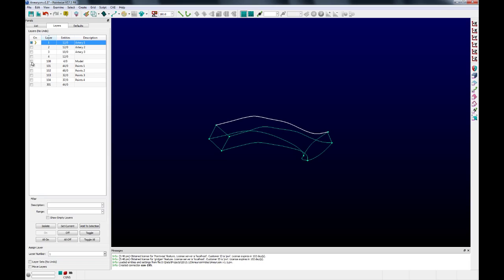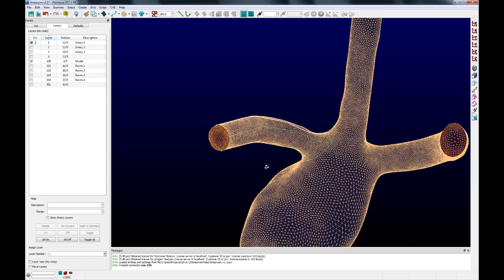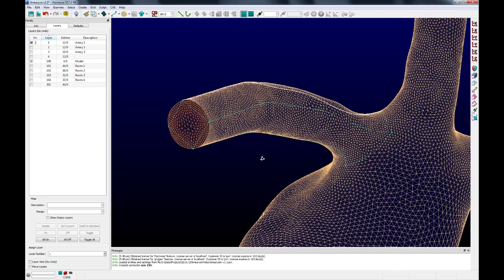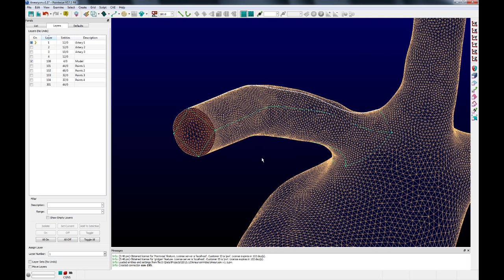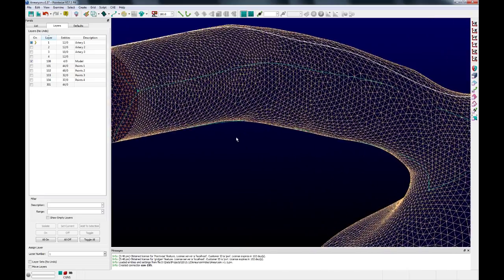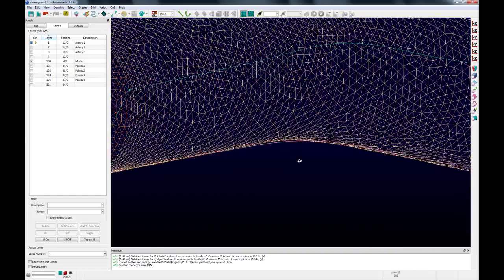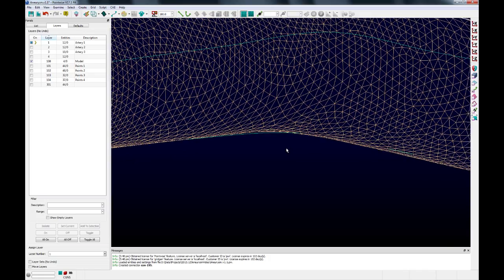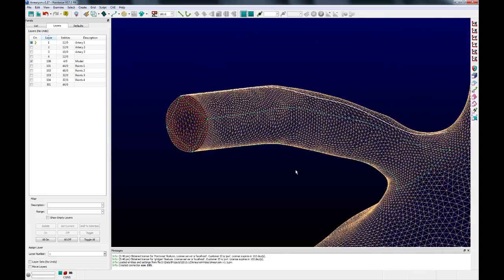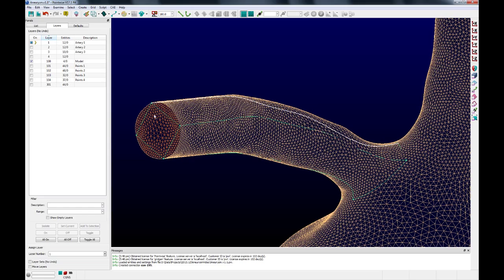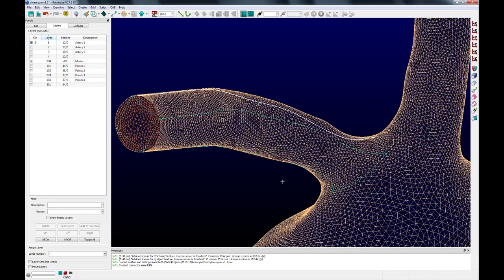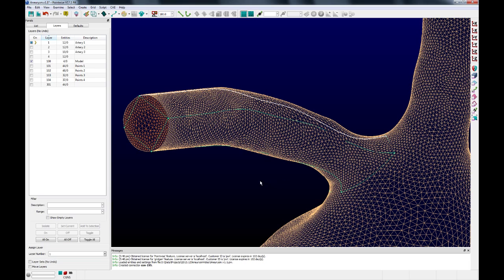However, at this point, the wireframe is not exactly conformal with the model, I apologize. The overall structure is close. We've got the right general shape, it's in the right vicinity, and point to point it's matched, because remember that each of those control points lied on the database surface. However, the overall wireframe is not conformal to the mesh. So what we need to do is actually project it onto the underlying database.